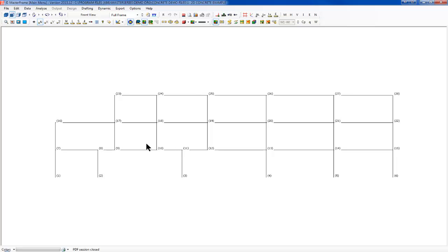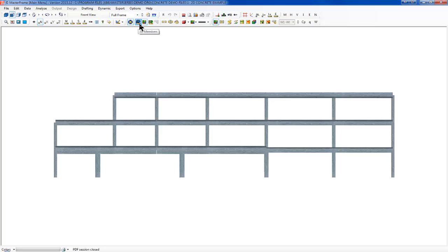First of all, it's a traditional plane frame, except we have some columns offset. We need to have wider spaces down below than up above, so we actually have these quite awkward little columns coming in the middle of beams, and columns stopping underneath beams as well. If we turn it on to 3D, we will see that we have quite large beams here, and then we have smaller beams. I'll just turn off my node numbers. We don't need to know about those.